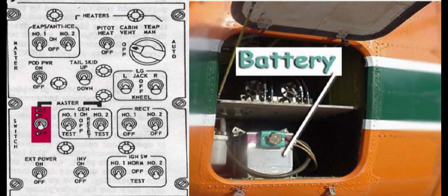The circuit breaker panel, labeled DC primary bus auxiliary, is linked to the primary DC circuit breaker panel and contains fire retardant tank, upper and lower hook, pendant load cell, and N1 and N2 circuit breakers. A lead acid battery supplies DC power when no other source is available.